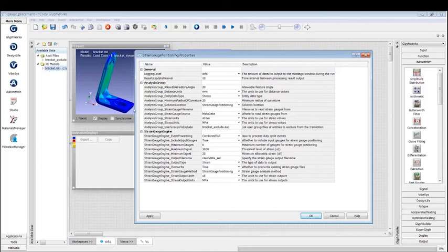And so we have controls here where we can specify breaks between elements, this feature angle. This 20 degrees here is basically if I have two edges of elements coming together and they form an angle that is off of 180 degrees by more than 20 degrees, it won't let me put a gauge at that node location, just because it's going to be a hard edge.